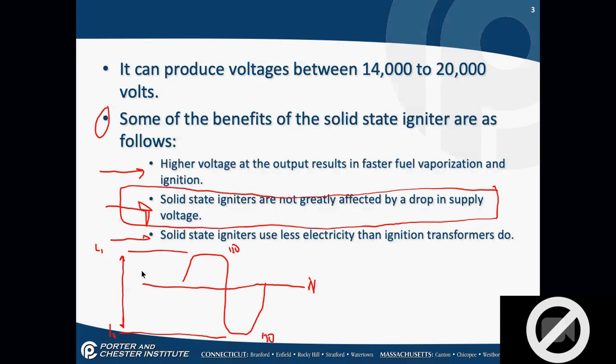That's how that works in your breaker panels when you have a double pole breaker. It's going from L1 to L2. Your single pole breakers for your lighting circuits, your plugs, your oil furnace are just going from neutral to L1 or neutral to L2. That's how we come up with our 120. Now, is it always 120? No. Everybody agree, no? Yeah, that's the correct answer.